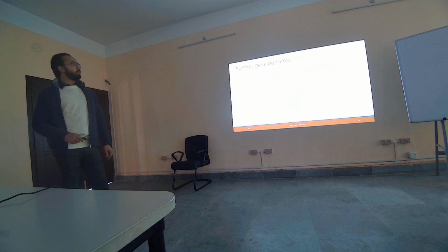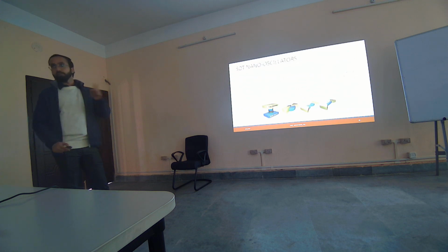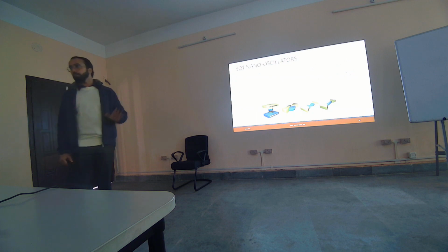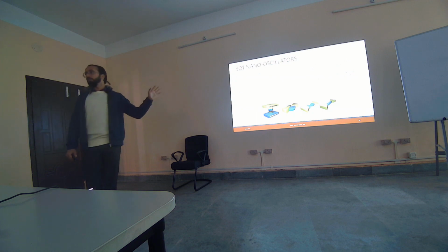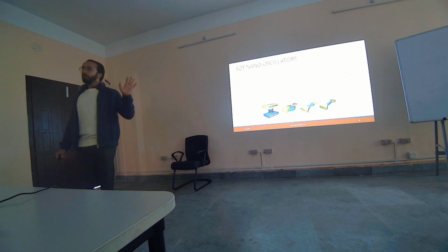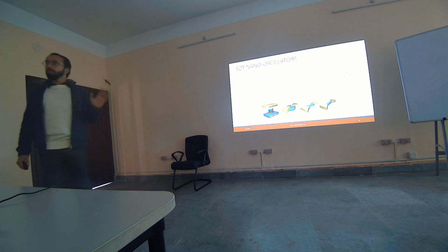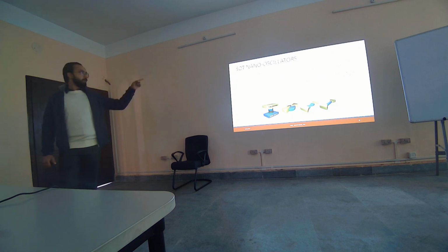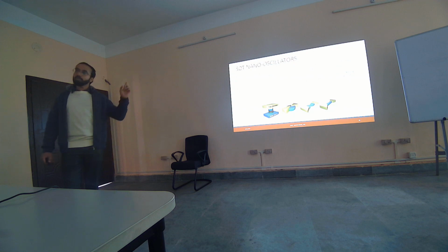Similarly, there are neuromorphic devices and spin torque oscillators. These are oscillators, and here I want oscillation, so I will use a low damping material. High damping and low damping both have uses. In memory and sensors we use high damping, but in oscillators and terahertz generators we use low damping.